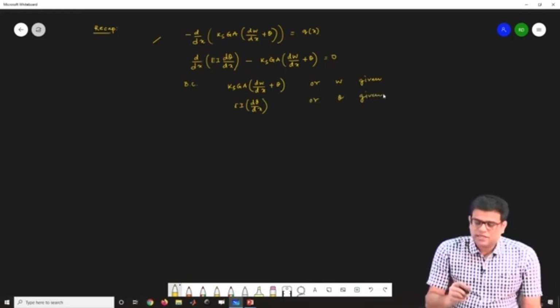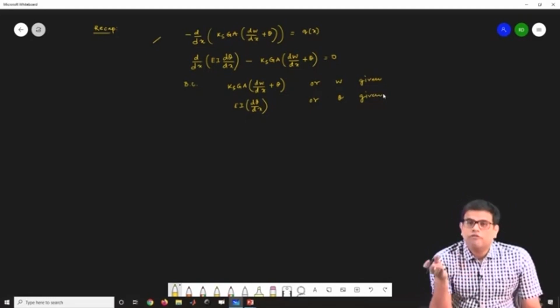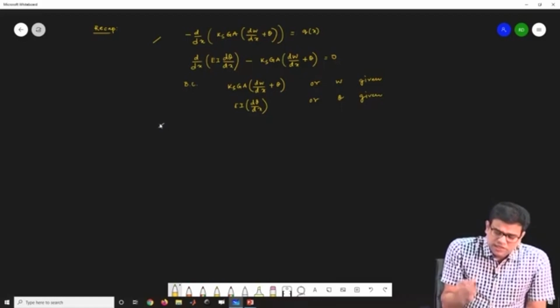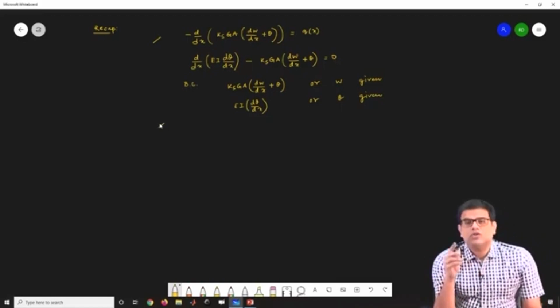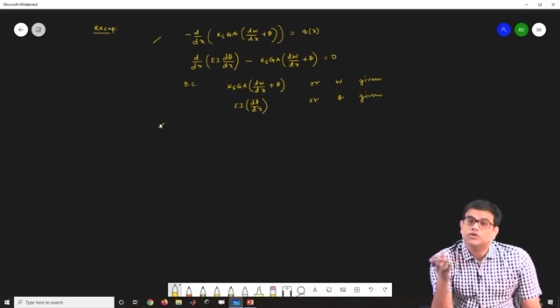So look carefully that for these two equations we have done the weak form, and then we did two interpolations, where we briefly introduced shear locking, the problem of interpolating w and theta with the same degree of polynomial. That leads to an inconsistent formulation, because w and theta in a thin beam limit should be almost equal, because it will follow the Euler-Bernoulli beam theory.